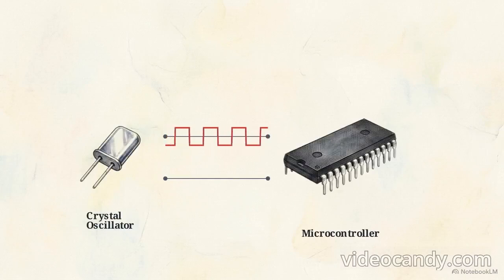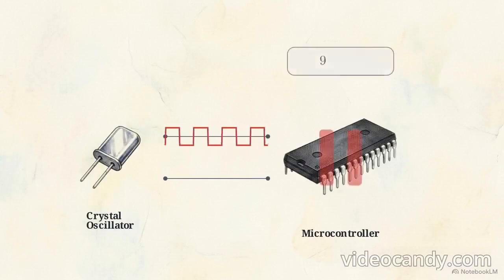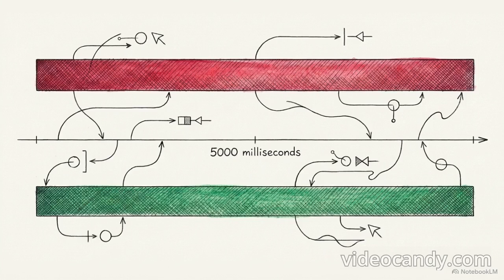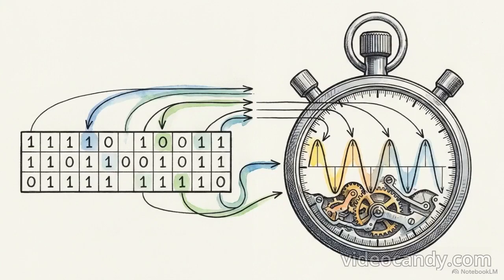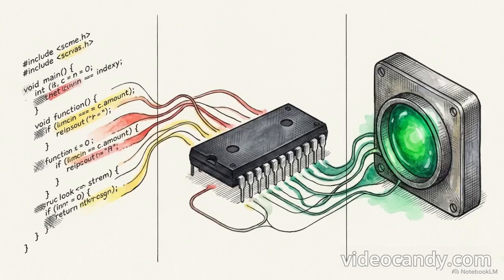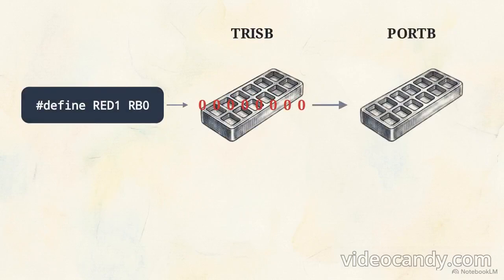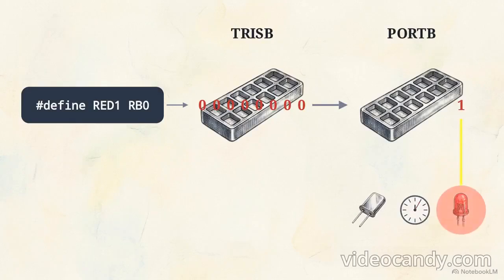In embedded programming, a delay function forces the central processing unit to freeze its instruction execution, calculating the pause by counting the physical cycles of the 8 MHz oscillator. By halting the processor, the microcontroller maintains the existing high and low voltages on the Port B pins for exactly 5,000 milliseconds. This sequence, toggling specific memory registers followed by hardware-enforced delays, forms the fundamental rhythm of embedded procedural control. Looking at the complete pipeline, the architecture of the system is clear. We abstracted the hardware pins into macros, locked the data direction using the TRIS register, and commanded physical voltage states using port manipulations and clock delays.